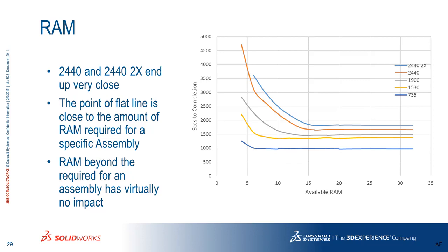Now, what I'd mentioned, the instability that you see when you don't have enough RAM, right here. The largest assembly we had could not even run at 4 gig of RAM. It couldn't finish, it wouldn't complete, it kept crashing, dying, we couldn't even get it to happen. That will happen to you if you don't have enough RAM for your assemblies. The swap was on, yes.